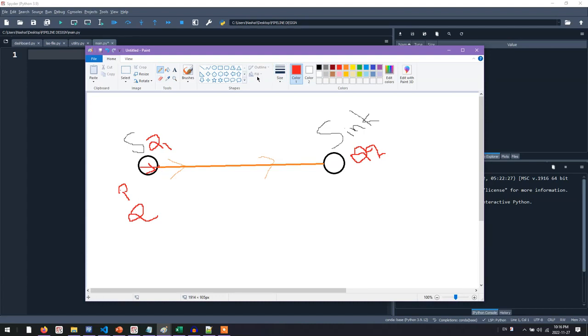Let's go back to the parameters in the source, and you have something called temperature. So those are the three basic inputs you usually use. And we have something else, which is the ambient temperature of the pipeline itself, meaning the air temperature around the pipeline. So these are all the basic information you need. Plus you need all the information about the pipeline, like the length, the diameter, the friction factor, and everything else. Plus you need the fluid properties like the API, the water cut, the GOR, and the gas specific gravity. So all those basic things.